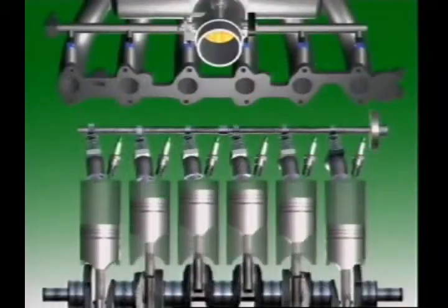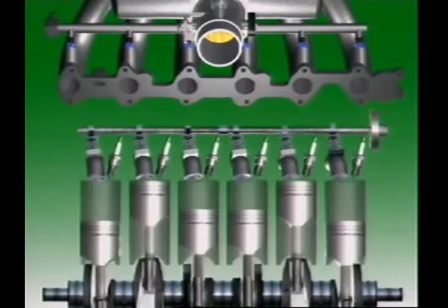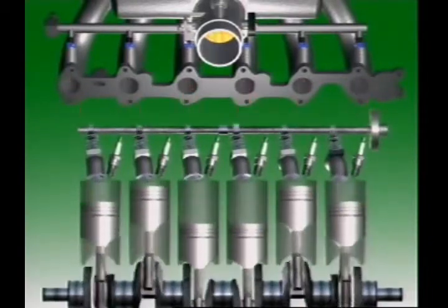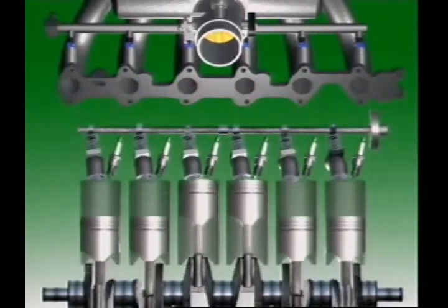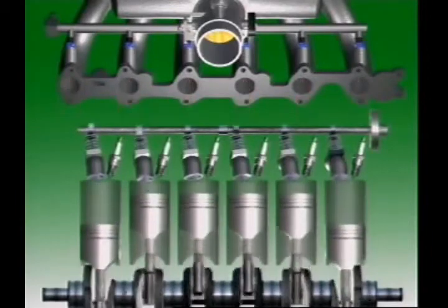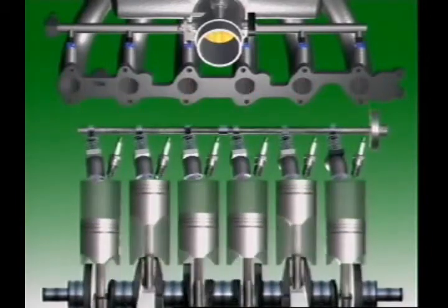During each engine cycle, the injectors open twice, and each time they deliver half the fuel needs of each cylinder. This happens regardless of the position of the intake valve. The injectors are triggered by the ignition system. So for a 6-cylinder engine, the control unit triggers the injectors on every 3rd ignition pulse.